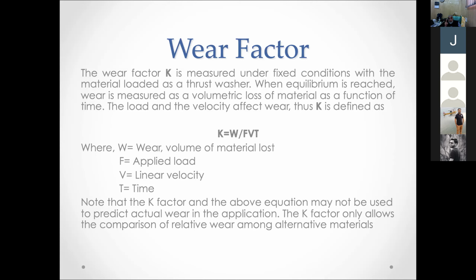Because if you know the coefficient of friction, you can know how much PV the bearing will generate. It will depend upon the coefficient of friction. If the coefficient of friction is low, the PV capability of the bearing material will be higher. If the coefficient of friction is high, then the PV capability of the bearing will be low. So wear will depend upon its wear capability. So we are using the wear factor to measure the wear of the material of the plain bearings.